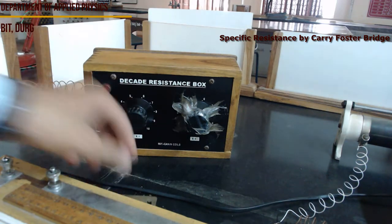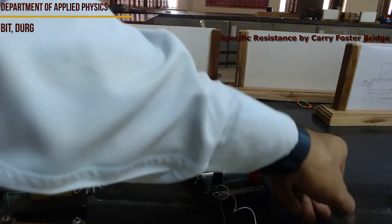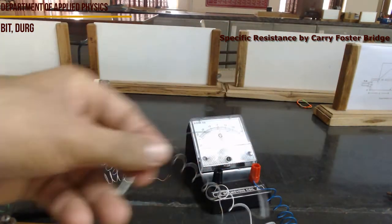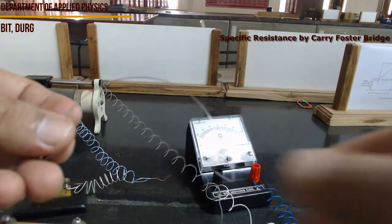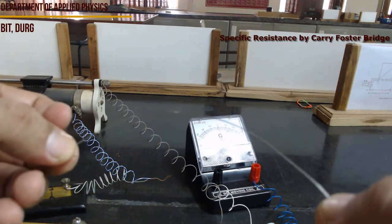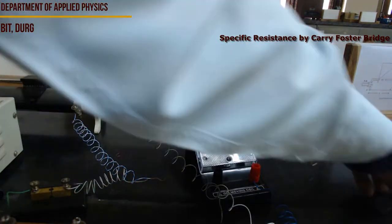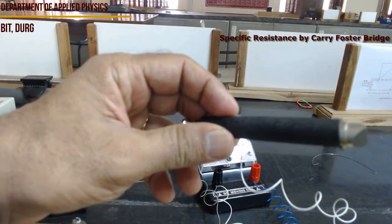Then we are having one experimental wire, the wire, the specific resistance of which is to be determined. This is that specific wire. It is cut in a length of say 15 centimeter, and there is a jockey for finding the balancing length in the bridge wire.